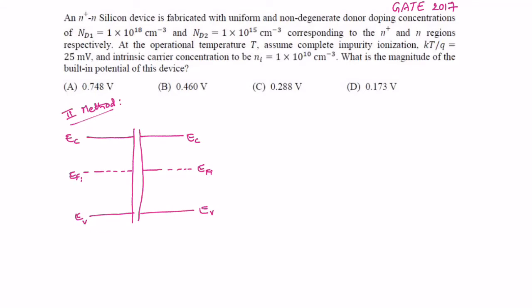EV is generally called as highest energy level of valence band. Okay, and we know that whenever a semiconductor is pentavalently doped, as the doping is going to becoming higher and higher, the Fermi level related to that n-type semiconductor moves towards conduction band, and it may touch conduction band or it may go deep into conduction band depending on the doping density.